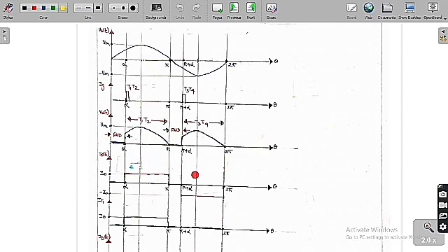So therefore we can say that full wave bridge rectifier plus freewheeling diode is called as a semi converter. So because of this reason only, because the output voltage and the source current graphs are the same as the asymmetrical and symmetrical circuits graphs. So this full wave bridge rectifier plus freewheeling diode combination is called as the semi converter. So because of this reason only.